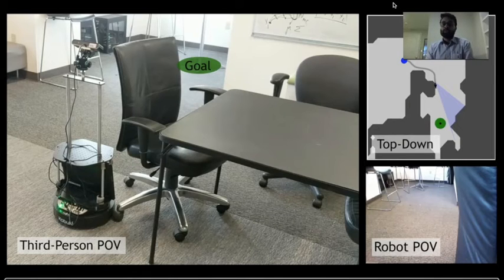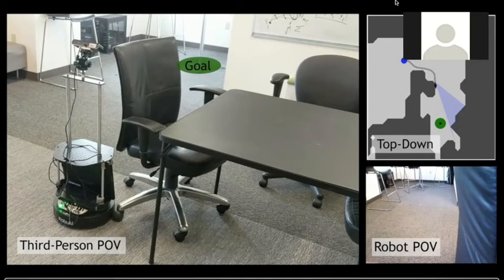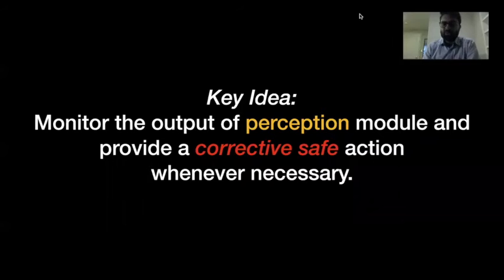Now, the challenge with the learning modules is that it is very hard to pre-characterize all these failure cases. And so we need some alternative safety mechanisms to ensure system safety in these kinds of scenarios. The approach that we have been taking in our work is that of monitoring. Here, we monitor the output of the perception module and only provide a corrective safe action whenever necessary. What that means is that we let the learning module do whatever it likes to do, unless it takes an action, or it produces a sub-goal in our case, which might lead to collision with something, at which point we provide a corrective safe action to avoid that collision.